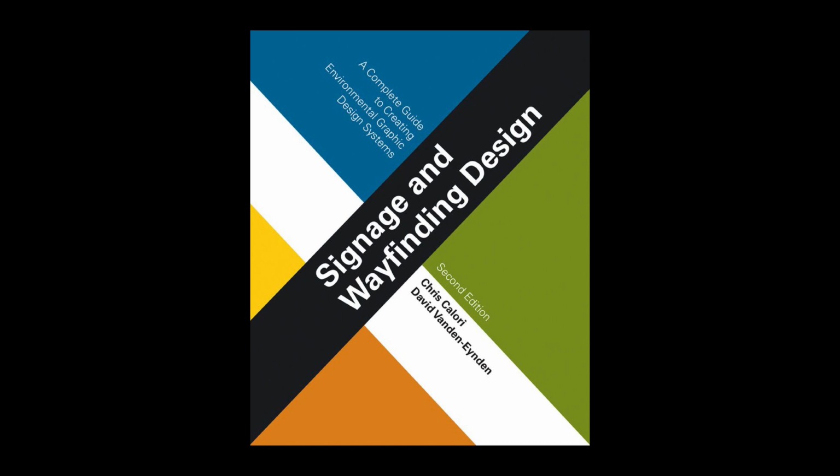Dimensions indicating where signs are positioned relative to their surroundings are also important. For example, a typical wall plaque mounting elevation indicates dimensions for the plaque's mounting height and distance from door openings. In addition to being dimensioned, all design drawings must be prepared at scales that can be measured with a scale ruler, typically an architectural scale ruler. See Figure 2.28. The smaller signs in a program can be drawn at full or half size, but larger signs have to be drawn at a smaller scale to fit on the drawing sheet.